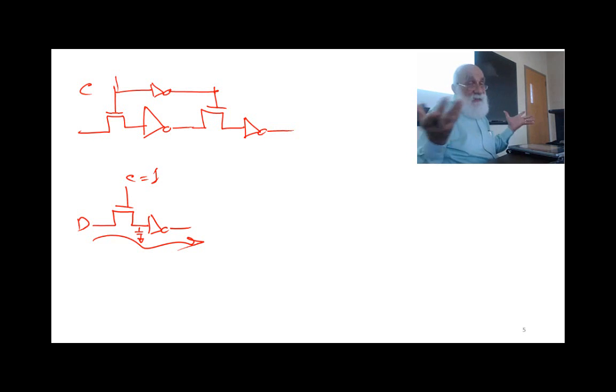And that is a good capacitance and holds data for some long time. Okay? So it is a latch. It looks like a latch. The only difference between this and the latch is that latch also gives me the true output. This only gives me the complemented output. However, it is like a latch. When C is 1, it is transparent.